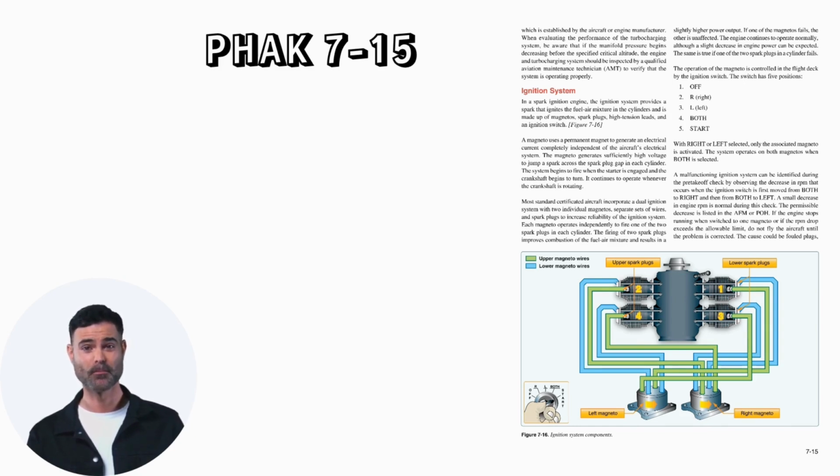When evaluating the performance of the turbocharging system, be aware that if the manifold pressure begins decreasing before the specified critical altitude, the engine and turbocharging system should be inspected by a qualified aviation maintenance technician (AMT) to verify that the system is operating properly.